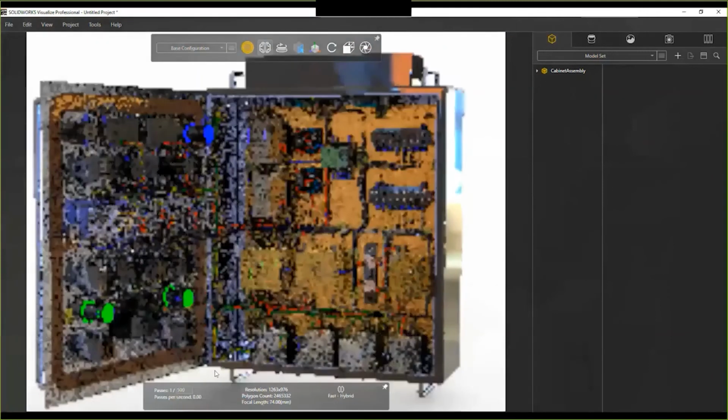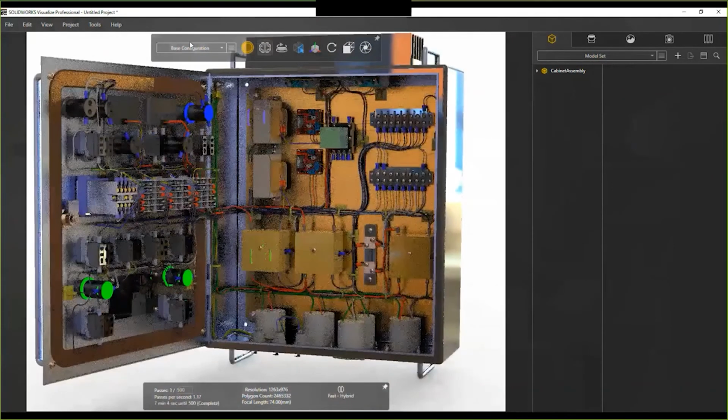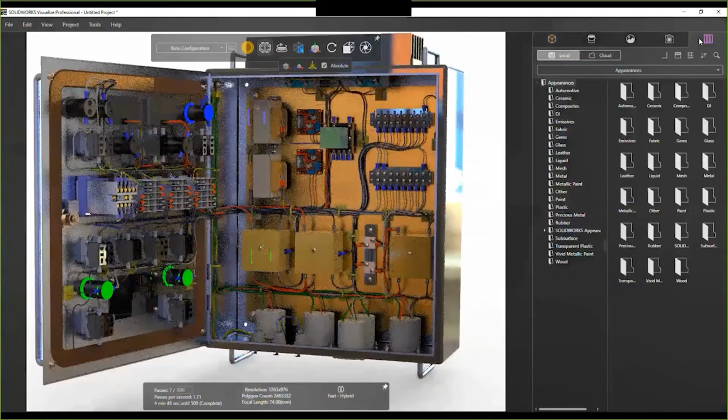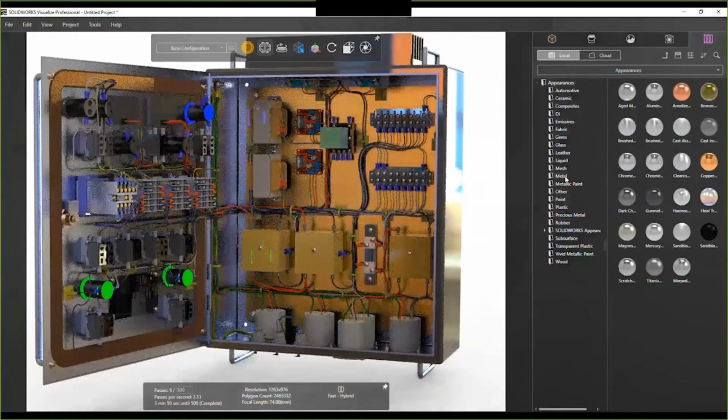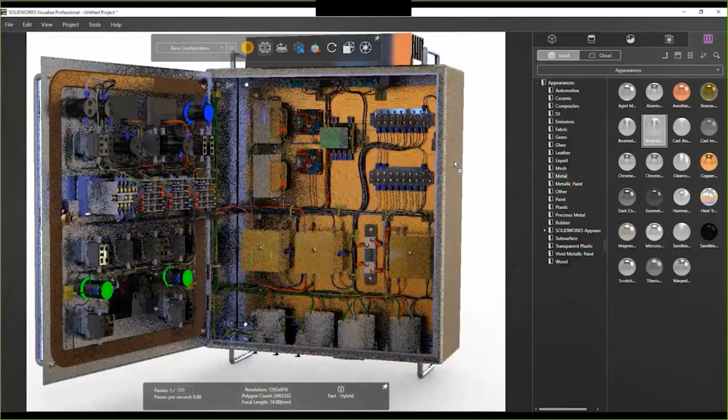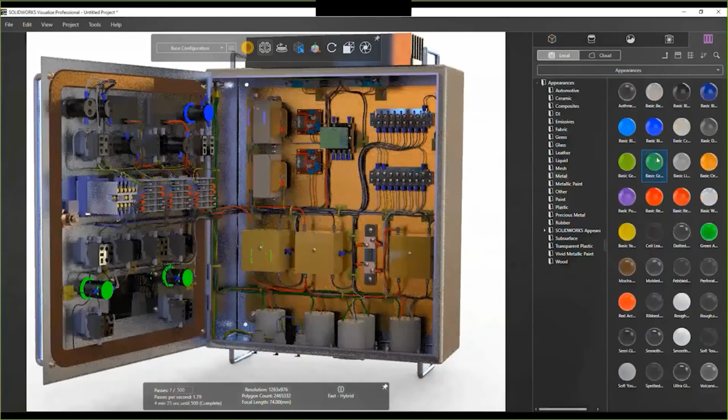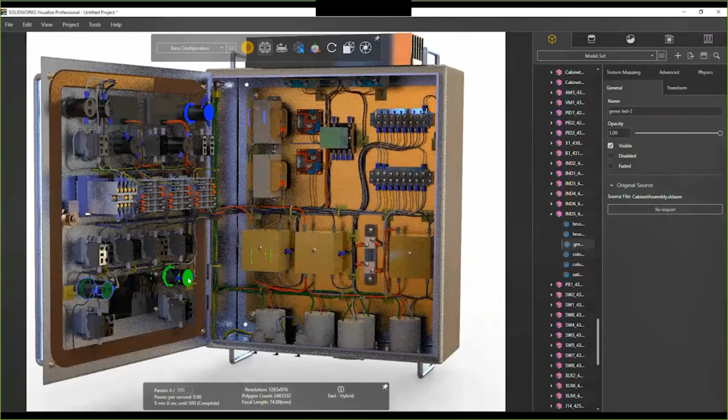Now, one thing I might want to do is begin to alter some of these appearances. Potentially this cabinet has maybe too much reflectivity on the outside, so the way that I can begin to change materials is literally just through drag and drop. If I wanted to add some more roughness onto the outside, maybe cut down the brightness of those LEDs over there, maybe I just want the color of it. I don't care too much about having that actual light showing.